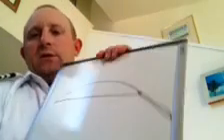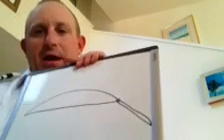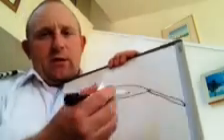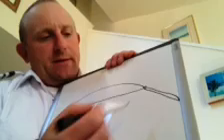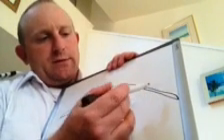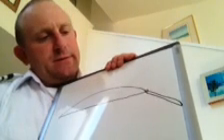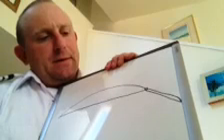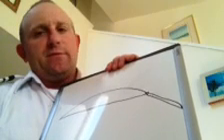We have several different kinds of flaps. The first one that I want to cover is a plain flap, which is pretty easy to understand. It's just a hinge device on the back of our wing, and it would look something like this. That would be our flap right there. This is called a plain flap, and it's going to increase the camber of the wing, and it's also going to really increase our induced drag, and that's a plain flap. And that's really the simplest type of flap.